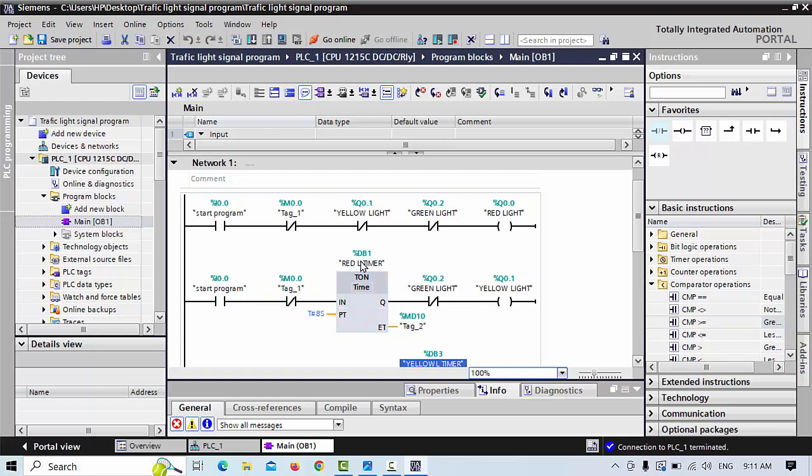example, that the client has a requirement at the crossing of the roads, in one area he says I need the HMI for my time running. I'd like to see which signal has how much time running. So I need to see this data on my HMI screen or pad or whatever display you like. So what you do, you simply go in here to these timers, and here you can choose